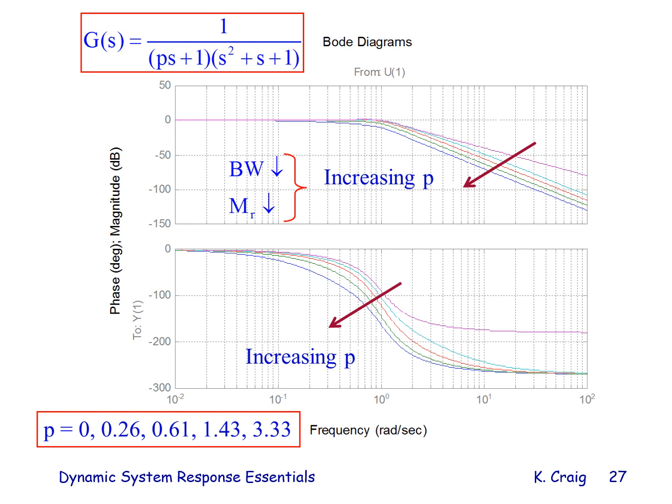These are good to remember, so when you're designing things or when you're just trying to predict how something's going to behave or change, if you add a zero or a pole, which is what we typically do when we implement control systems. Lead and lag controllers are simply the adding of poles and zeros to transfer functions. So when we talk about controls, this is very, very relevant. It allows us to predict very quickly, with great insight, what the effect will be.